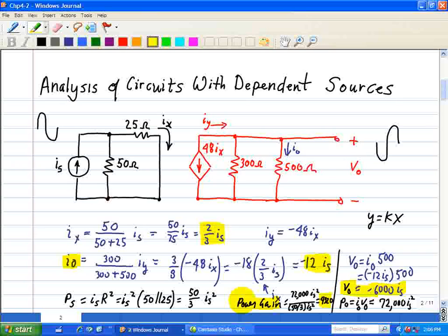is much greater than unity, which means that the circuit delivers more power at its output than it receives from the input source. At first glance, this appears to be a violation of energy conservation, but we have to remember that dependent sources are models of active devices that require an external power supply to operate.